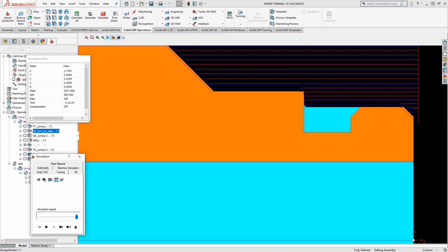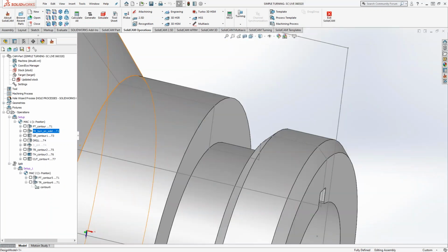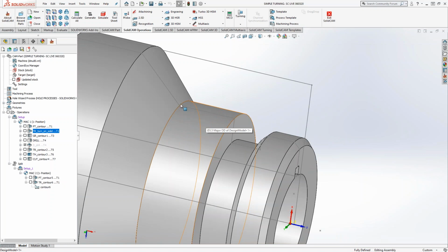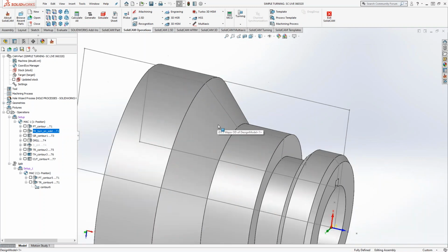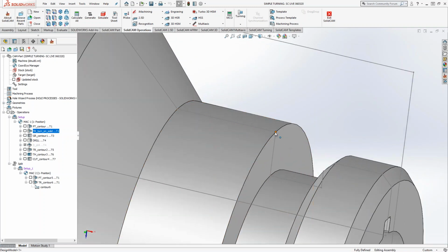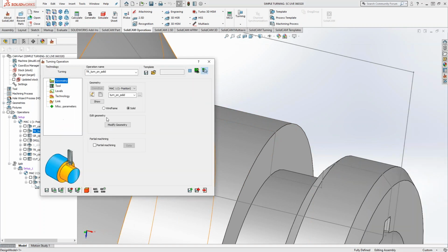So the movement of the tool is leaving that sharp corner there, and we probably want to break some edges on that because that probably is not where we want it to be. And obviously, this sharp corner here is not even possible. Our insert has a corner radius, so we definitely want to leave something there. So let's take a look at external and internal corners in that tool path. So open that guy up.